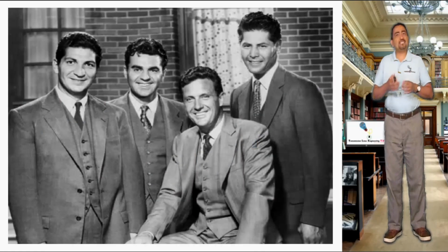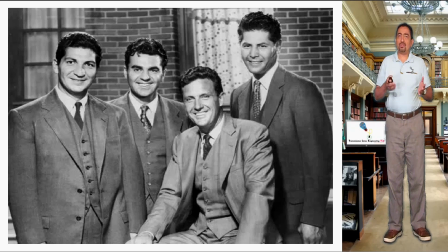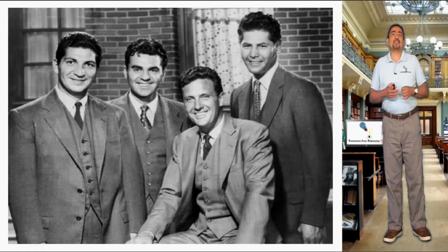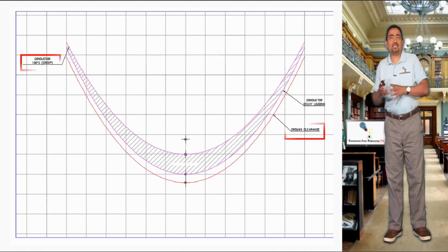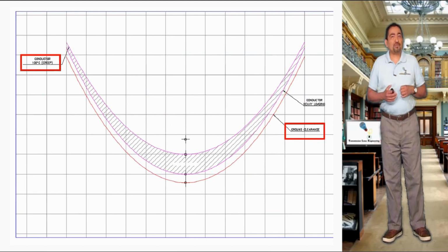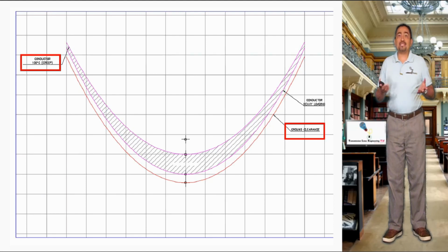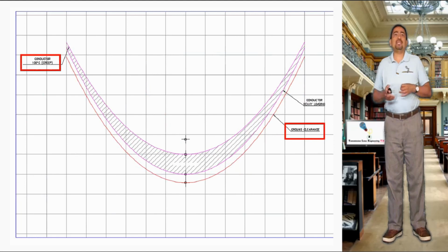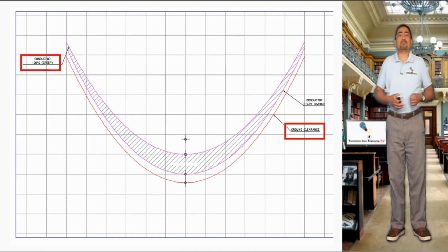By the early 1930s, the concept of constructing the catenary was introduced, based on the mechanical calculation on an acrylic template, and parallel to this one, a second catenary was drawn, simulating the required clearance to the ground. The result was the first structure location template. This idea became the tool that even today continues to be the accepted method for structure spotting, on which modern software for structure locations is developed.